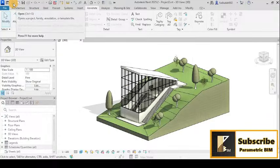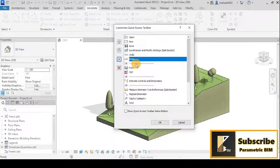So this is up to you. You can arrange the quick access bar as you want from here. You can also add a separator. For example, if I click here and add a separator, it will give me this separation between the redo and the print. You can categorize your commands as you want from here, or you can delete any of them from here, or you can delete the separator from here. So this is up to you.